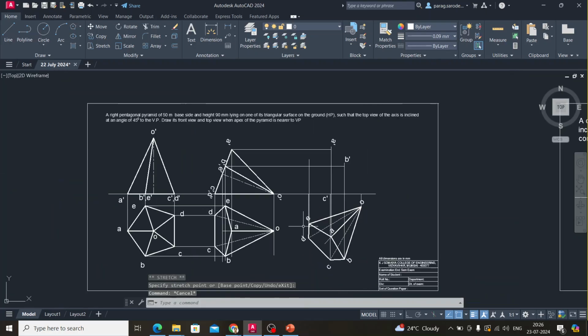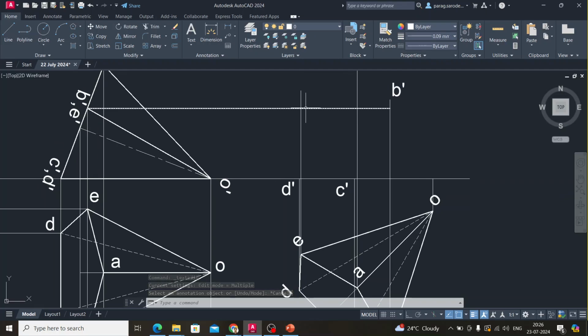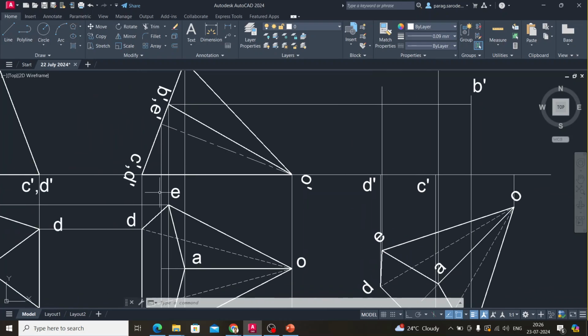Where is our D dash? Closely look. D dash is on the left, right? And this right projector is for the E point. So I'm copying this C and I will place it here and I will rename it as D. Okay. Now where is E? E is here, which is on the horizontal line passing from the BE and projected from E here, right?